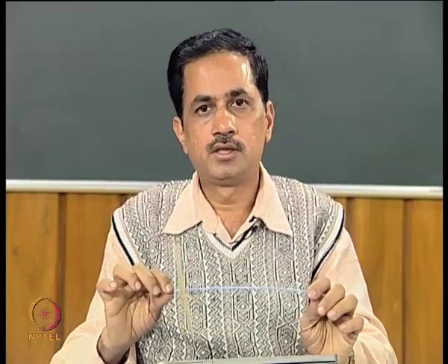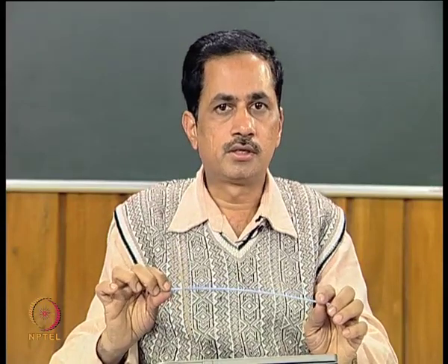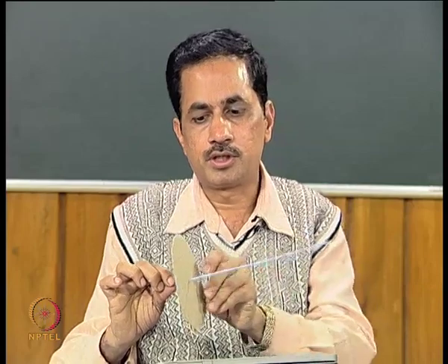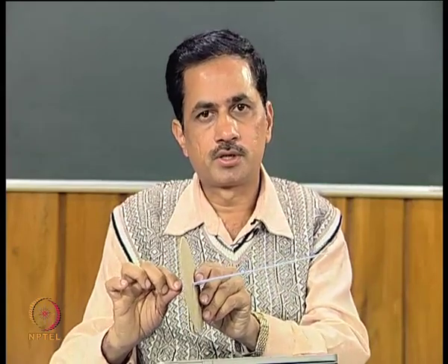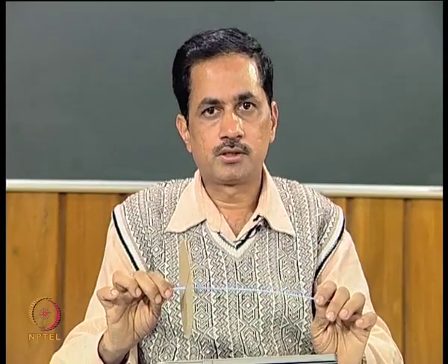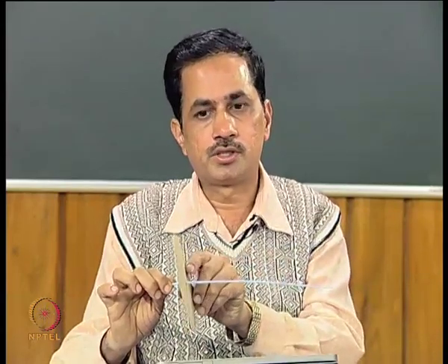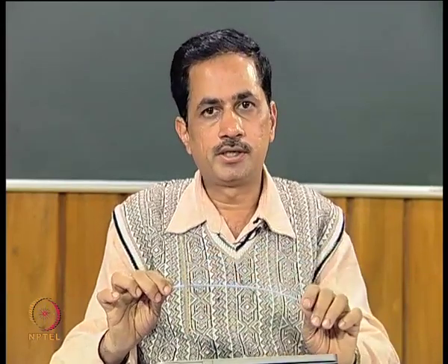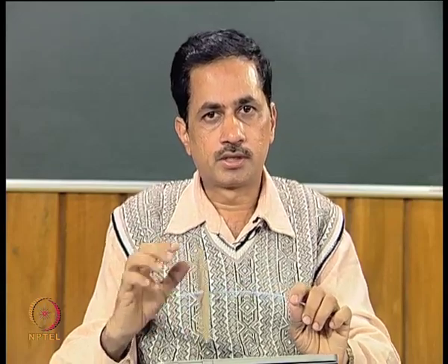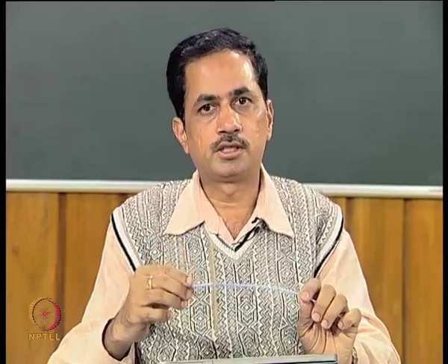In a subsequent lecture we will try to derive the equation of motion of this kind of disk without considering the gyroscopic couple, and initially we will take the 4 degree of freedom system and we will obtain the corresponding 4 equations of motion, that is 2 in the translational direction and 2 in the tilting. This particular tilting is different from what we considered initially in the case of the Jeffcott rotor, where we considered the torsional displacement theta.